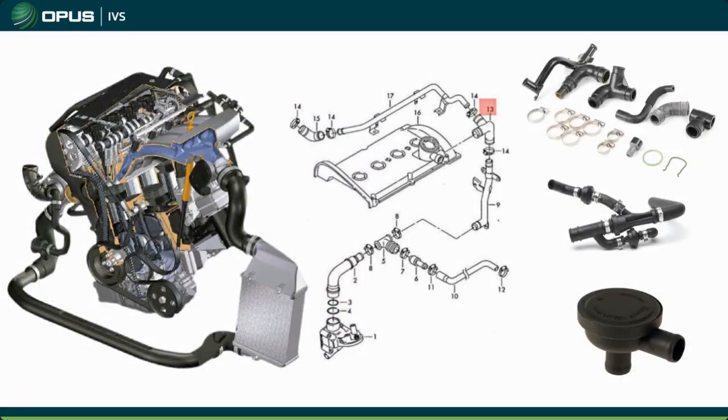And you can get a freezing of the water mixture in the vapors, and that can lead to all kinds of issues. So it's something to definitely keep in mind that leaks in this system can cause freeze up if you have a lot of moisture and very cold temperatures. I have seen these things freeze up. I've experienced it myself on a Volkswagen GTI I had, where on cold start I was just burning tons of oil, and I found that the thing was full of water and it was all frozen. And once it warmed up, everything worked great. So, I mean, it is something to keep in mind.